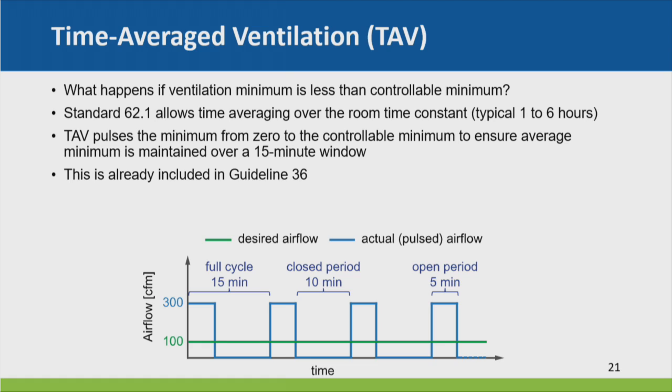However, we did find a flaw in our sequences, is that because loads are so low and we're often at the minimum all the time, we ended up where all the boxes closed at the same time, and that didn't work very well. So a fan tripped off in high static. I think we blew off a flex duct or something. So we have some added logic that randomizes, so we pass a token that says, okay, you can go down to 0, but the other guys can't, to try to make it so that not everybody goes down at the same time.